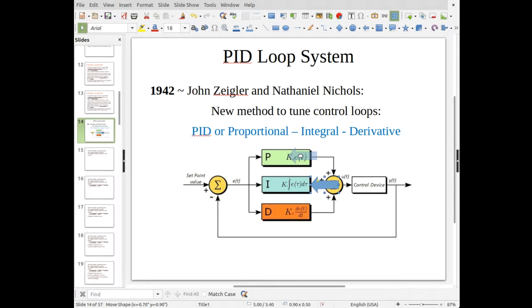See, the proportional control totally forgets. When we go around the second time, it totally ignores the fact that we had error the previous scan. It doesn't pay any attention to that. But an integrator remembers, hey, I had some error last time around, and I remembered what that error was.